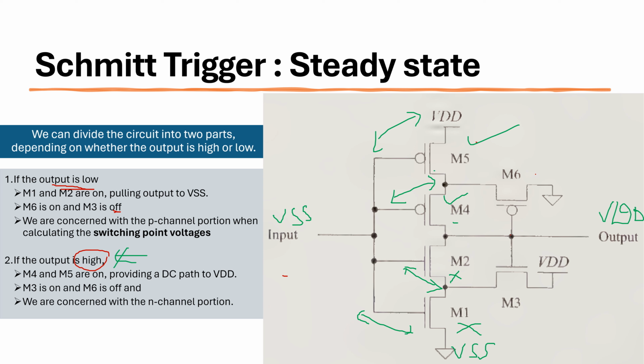Okay, let's look into these two things now. Let's look at this one first. This is at VDD gate and this is closer to the VDD only. So VDD minus VDD, VSG is equal to V source minus V gate. It means this VSG is lesser than VTH. Of course we are talking about the absolute value. So lesser than VTH, so it is off.